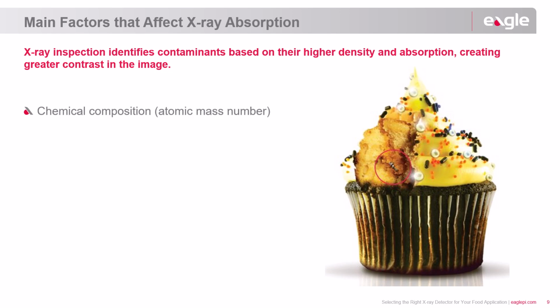1. Chemical composition. The ingredients in your product affect the X-ray image. For example, products high in salt produce denser images because chloride absorbs X-rays well, resulting in darker areas. 2. Product thickness. Thicker products require stronger X-rays to penetrate and detect any contaminants inside effectively.